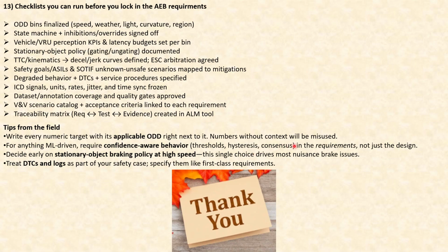Confidence aware behavior in the requirements is a must, not just in the design. And decide early on the stationary object braking policy at high speed. This single choice drives most nuisance brake issues. Treat DTCs and logs as part of your safety case. Never ignore DTCs, because these are extremely important when it comes to ADAS.